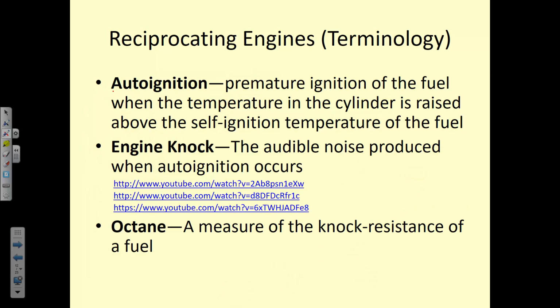Auto ignition is premature ignition of the fuel when the temperature is raised above the self-ignition temperature. And this is desirable in a diesel engine. It is very undesirable in a gas engine. You want spark ignition. And engine knock is what happens when that auto ignition occurs.